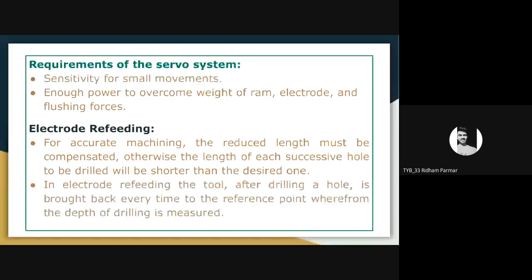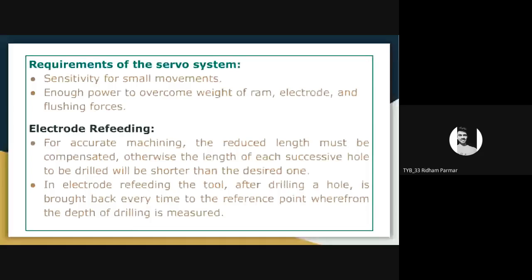Okay, and if the flushing of the gap is not clear, then the machining cycle time will be long, and vice versa. Here, two requirements of the servo system are small movement and enough force for the flushing. Okay, now I will talk about what electrode refeeding is.